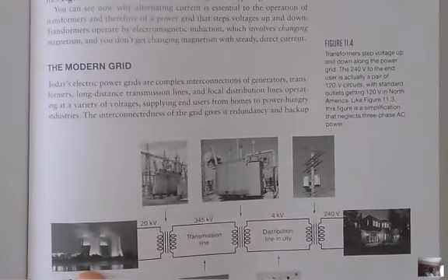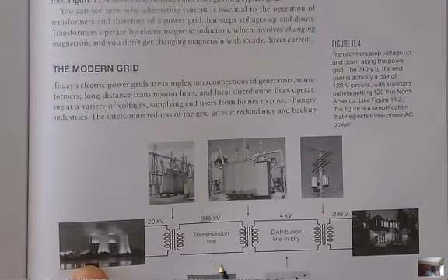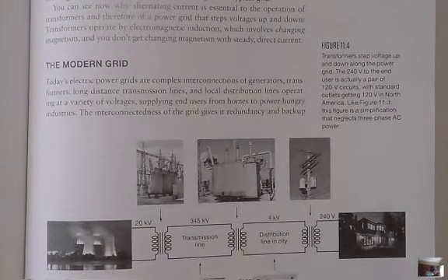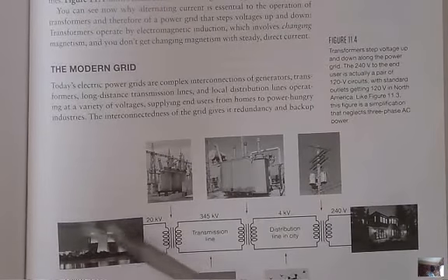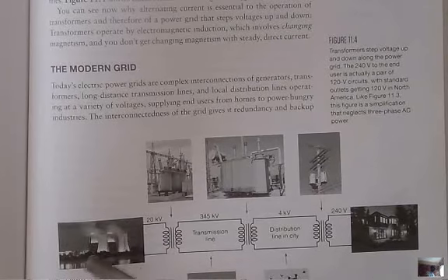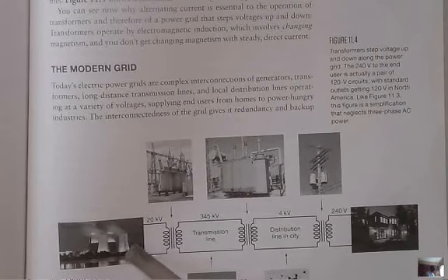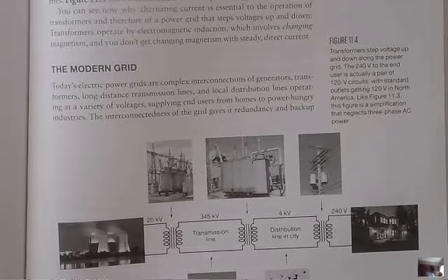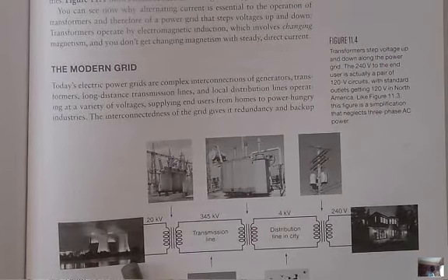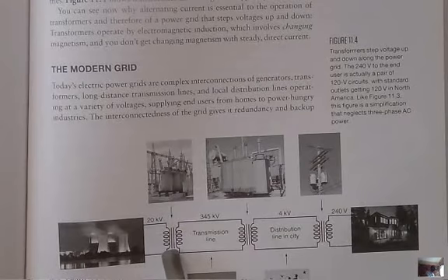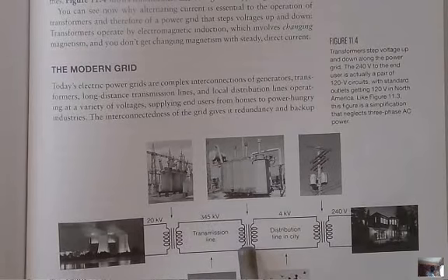So here's the power plant. It doesn't matter what kind of power plant it is. Almost all power plants have these really cool cooling towers to cool the hot water off. It doesn't have to be nuclear to have that. This could be our Bergen County gas-fired power plant that you see when you're on Route 80, by Ridgefield Park. Power leaves at 20 kilovolts, goes through a transformer, gets jacked up to 345, and makes it miles all the way to your town. Let's say your town is in Hackensack.